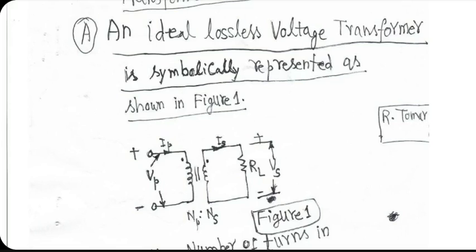We are assuming load to be a real quantity, that means a resistor, but it doesn't have to be that. Okay, so this is the simplest description you can think of when it comes to a transformer. VP divided by VS equal to NP divided by NS, and VP IP equal to VS IS, assuming power factor is 1 and all that, and losses are 0.